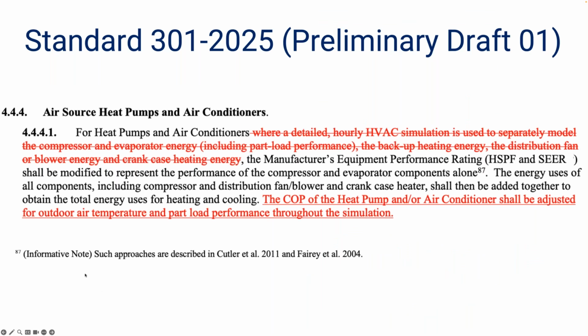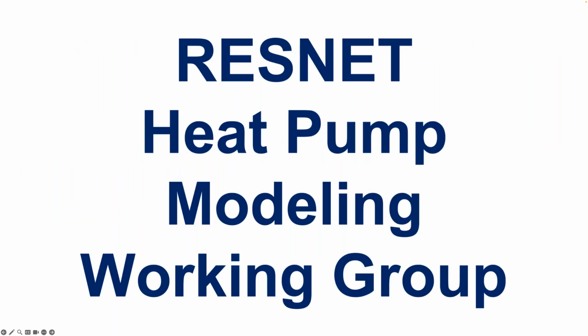So this paragraph that is in the standards right now says a lot about what to do, but not much about how to do it. And as a result, there's a wide range of interpretation, and any consistency across software tools is either informal, as I mentioned, all referenced in the same document, or just kind of coincidental. And so to resolve this, we wanted to make a lot more of this normative standard language that this is how you should go about modeling heat pumps and air conditioners. So we established a working group to develop the standard language to codify most of these best practices.